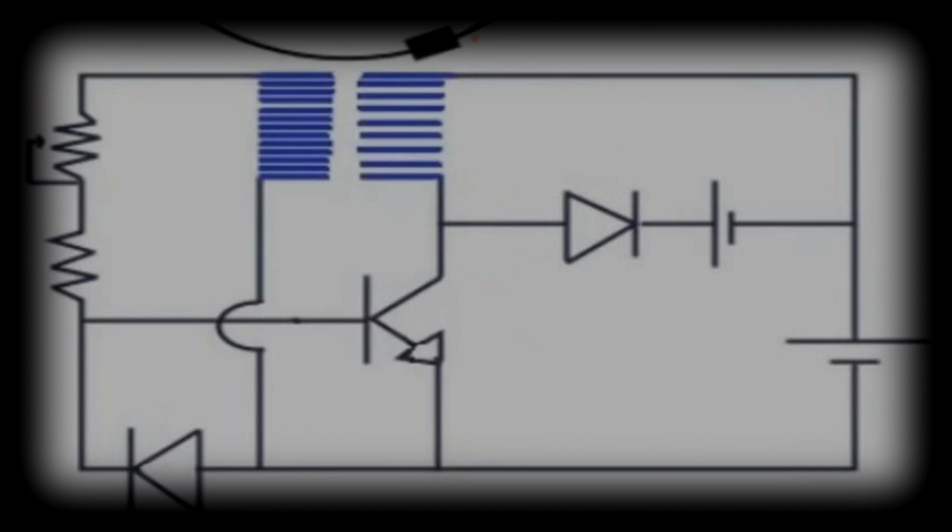So again, it starts here, goes there, gets closer to the trigger winding, biases it in that direction, plus arrow pointing down, reaching to the minus of the same coil on the other side. That's the trigger coil. Then the magnet gets even closer to the trigger coil.